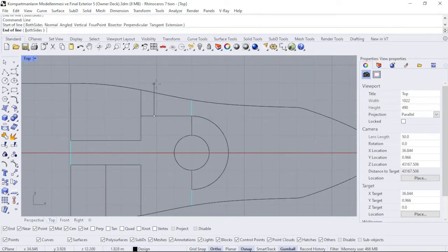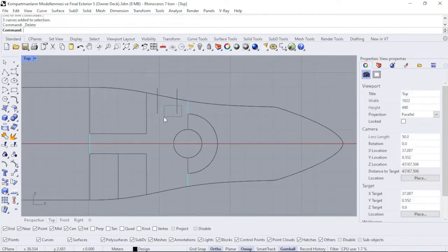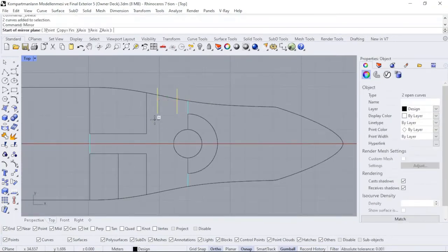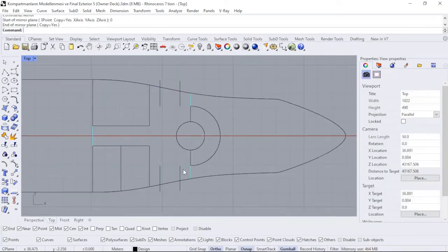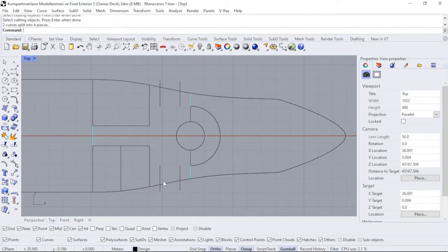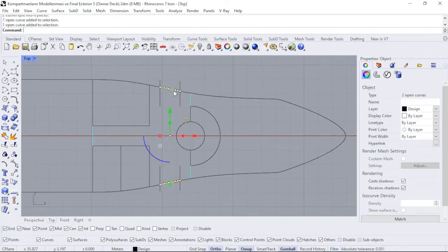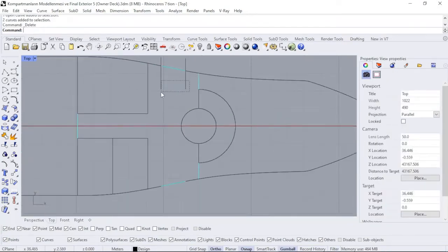Then holding the ends, I draw two more lines vertically. Afterwards, I can delete all of the curves here. Then I get these curves symmetric to the other side. Next, I enter the split command. First, I select the part to be split and press space, and I select the parts to split. I complete the split operation by space. I want to make the color of these curves cyan too, then I can delete the black curves.